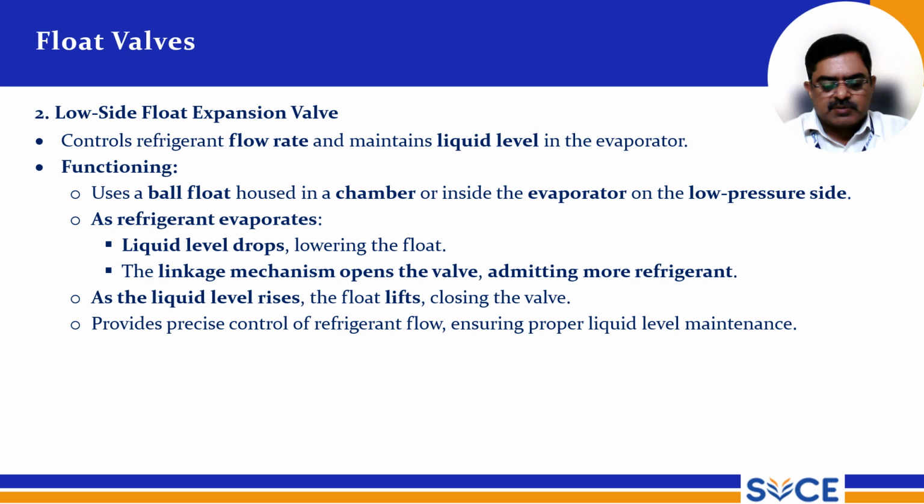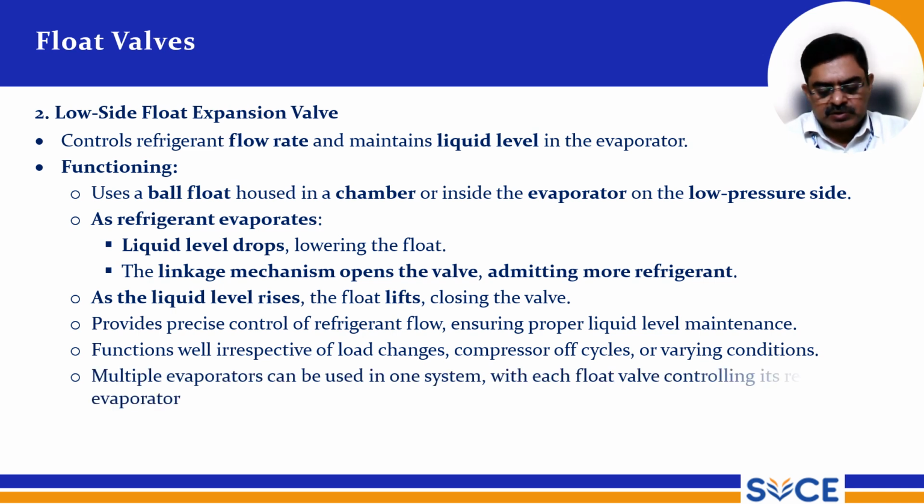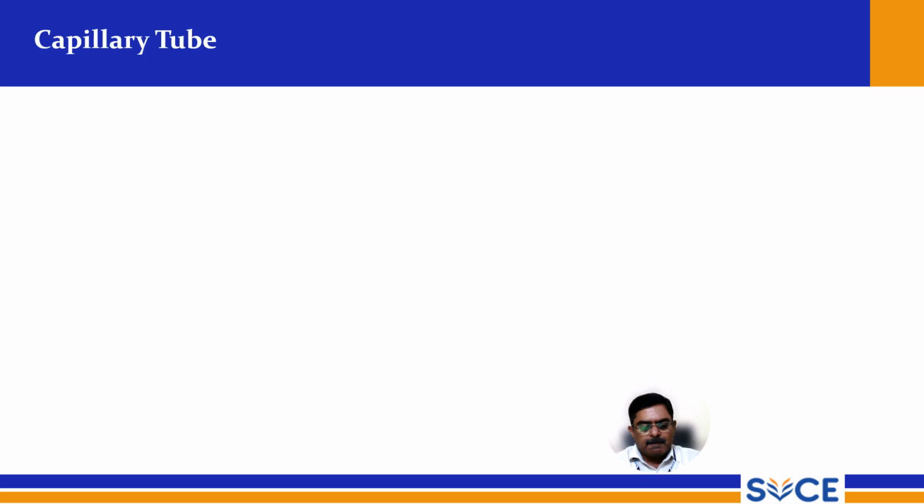So it provides precise control of refrigerant flow, ensuring proper liquid level maintenance. It functions well irrespective of load changes, compressor off cycles and varying conditions. Multiple evaporators can be used in one system, with each float valve controlling its individual evaporator.